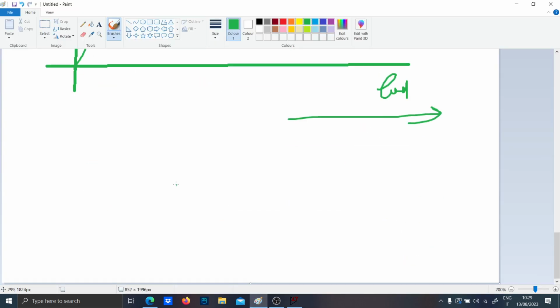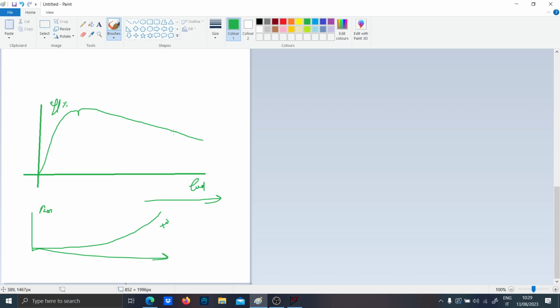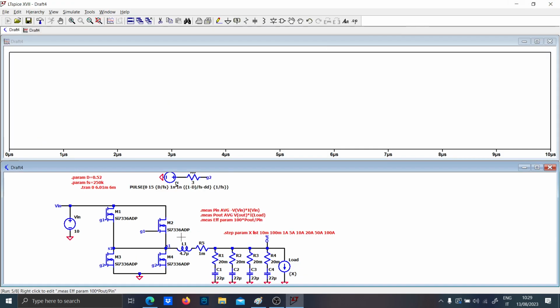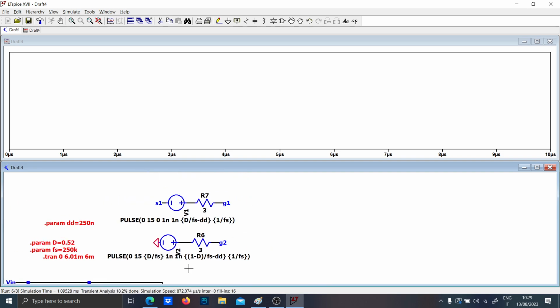So basically now you are confronting a lot of things: the efficiency and also the power loss. The power loss will increase basically quadratically with your circuit, and here you have the dead time losses, the switching losses, the output capacitance COSS losses, so all the possible losses that you can have in a switch, and also the gate resistor losses, of course.